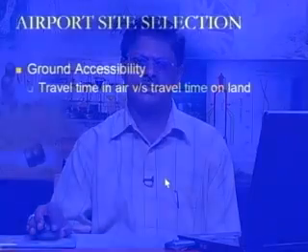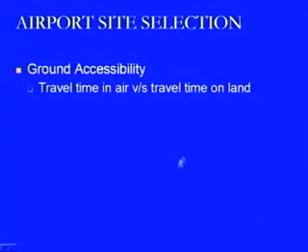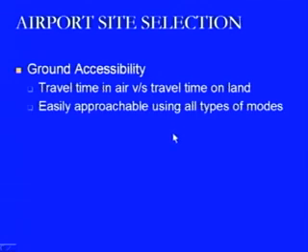The next point is ground accessibility, which is a very important point, because we have to look at the time it takes for us to travel from the city to the airport location, and if this travel time is more than the travel time taken in air, then obviously there is no use of providing that type of facility. So, we have to correlate and make a trade-off between the travel time on ground and the travel time in air.